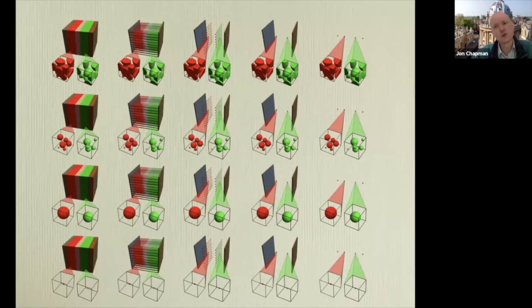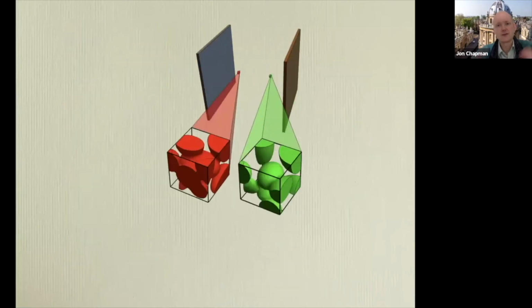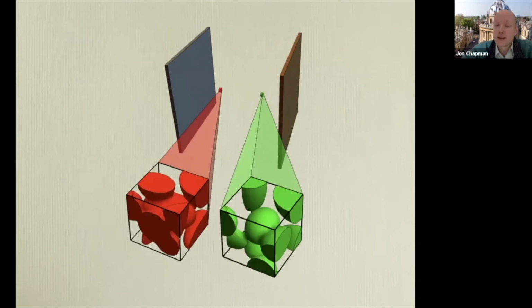And of course, you can do that and then say, well, the current collector is a little bit more conductive even than that, and then you would get effectively a single particle model with an in-series resistance that you can calculate due to the two-dimensional current collector.